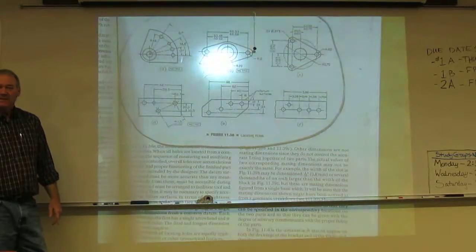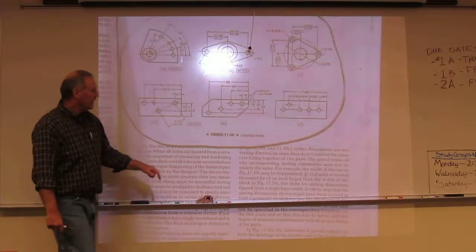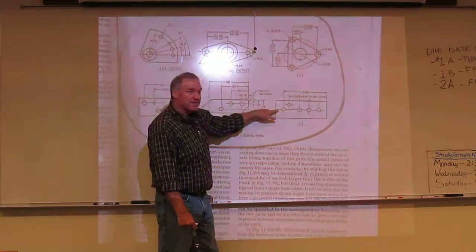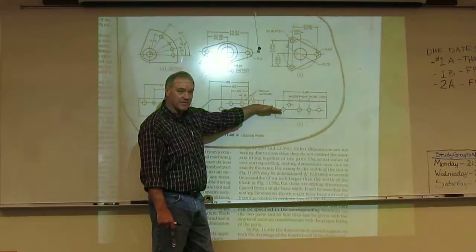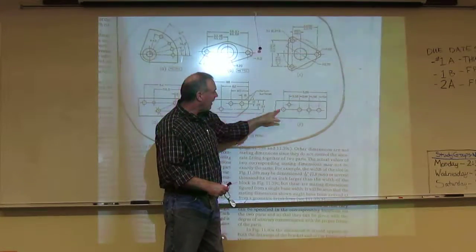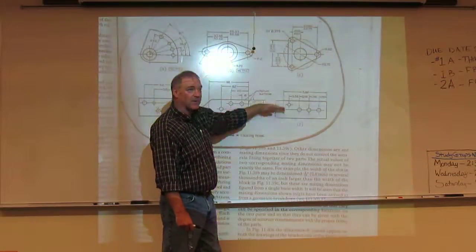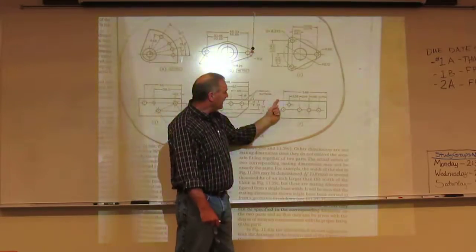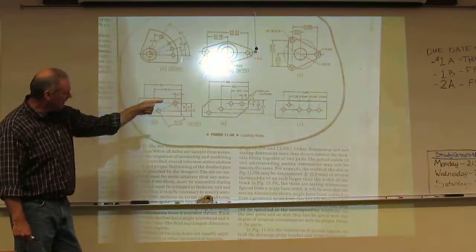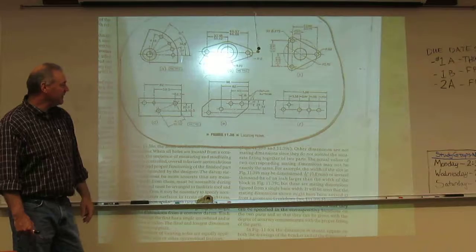Nice example of using center lines to remove dimensions off of them. Again, you see that also right here, where notice these are all sitting on the same y-axis point. That only needs one dimension, and you've located in a y dimension all 4 of those. I would need another one for this one in the y direction, but then in the x, I'm pulling off, they're doing chain dimensioning here. Kind of like how they've switched the arrows around, because we're too small to get everything to fit.